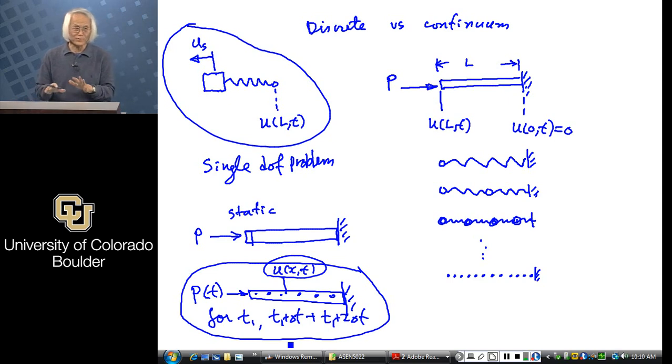So I just want you to see there are 3 things in this simple chart. In discrete cases, if you decide the number of masses, that's the degree of freedom. In the continuum case, there will be infinitely many infinitesimal masses, and each mass is associated with its own unique dynamic characteristic. When you look at the entire system for n masses, in reality, you can get the continuum solution or approximate discrete solutions. The more degrees of freedom you throw in to approximate the continuum, the more vibrational characterization you are infusing into the system. And this is the challenge of modeling continuum problems, or in general structural problems, in dynamic cases by the finite element method. Okay?